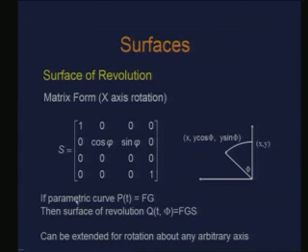Now, if you recall, a parametric curve P(t) can also be represented in matrix form, where I have these f which are nothing but some sort of blending functions, right, where I can also construct those in the form of monomial polynomials, right, 1, t, t square, t cube, and the associated coefficients, and some information of geometry which is g, right.